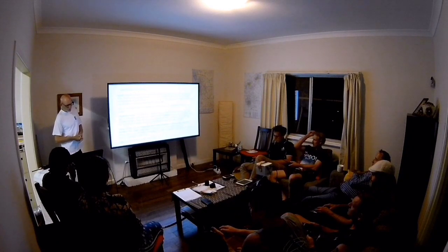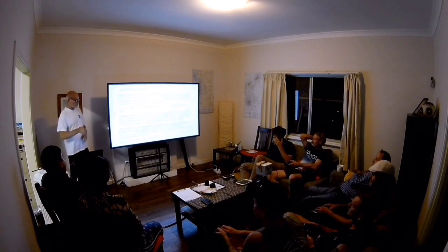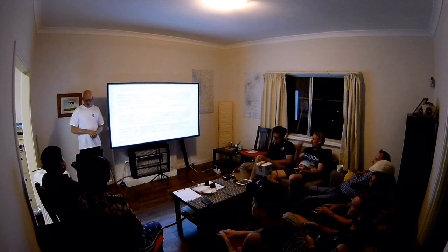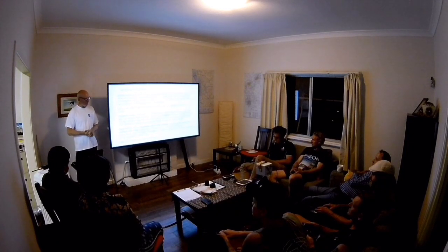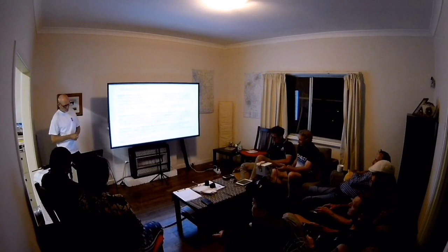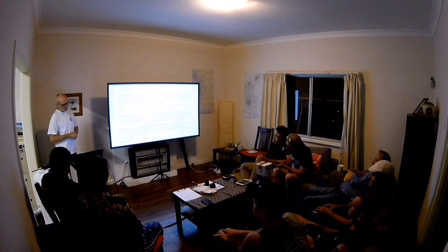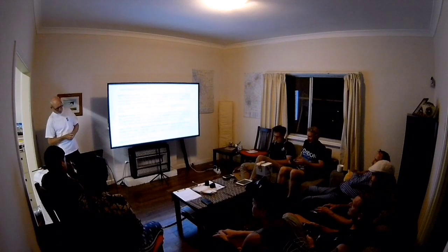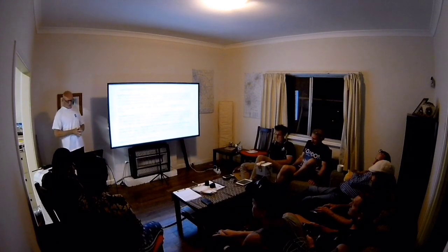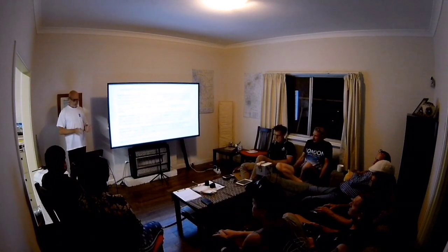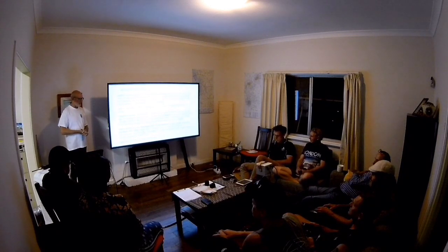If the signal is weak, you may need to turn that squelch button down so that you can hear that signal, in which case you will get that hash noise also. Note, if you leave a radio on standby with the squelch turned down, you will get that static noise and it will eat up your battery quickly.